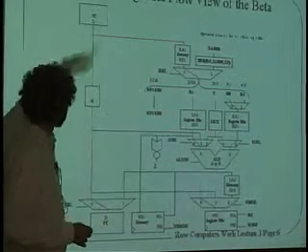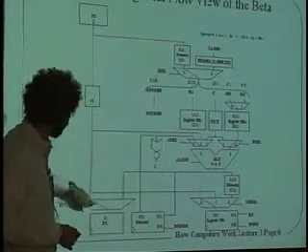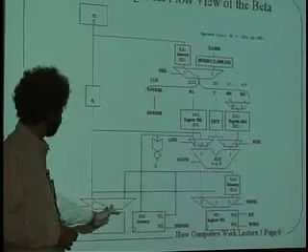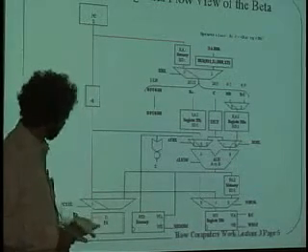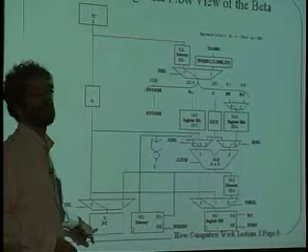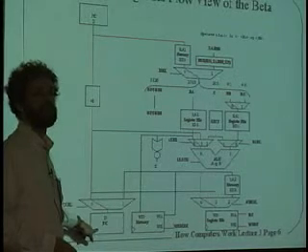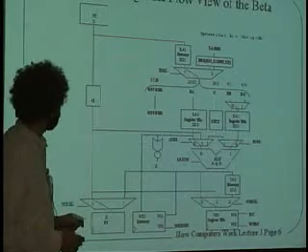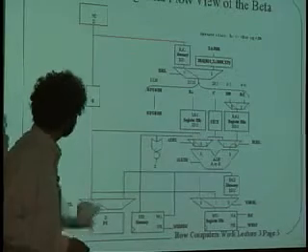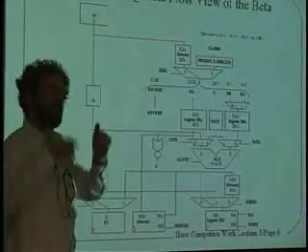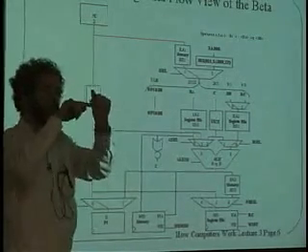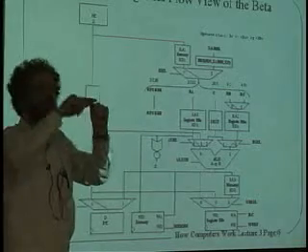So PC gets incremented by 1, gets chosen by this selector here by choosing the left-hand side, and then gets written back into the PC right here. And that's how we increment the PC. Most textbooks will show you this drawn with these two boxes as one box and a loop showing you PC gets PC plus 1 and a loop going back to the top.